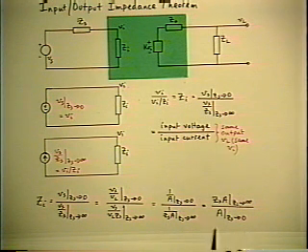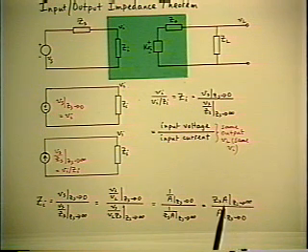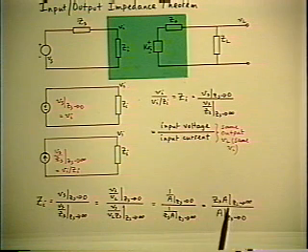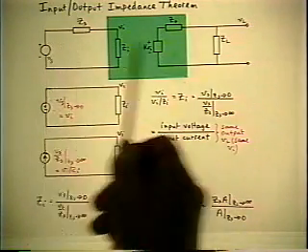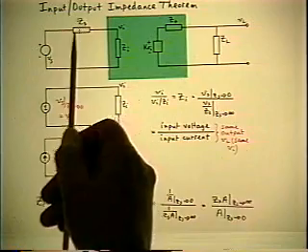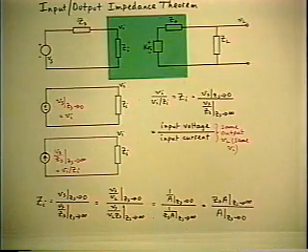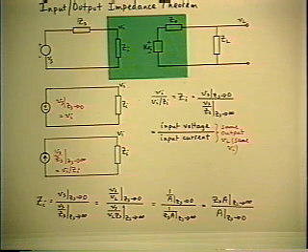And it's very similar to the output impedance theorem, which says you've done all the work already to find the A, and then to find the input impedance, all you have to do is take two simple limits. And the Zs is inside the A, because the Zs was in the model when you solved for it. It's almost too good to be true, isn't it? I mean, it's just ridiculously simple.